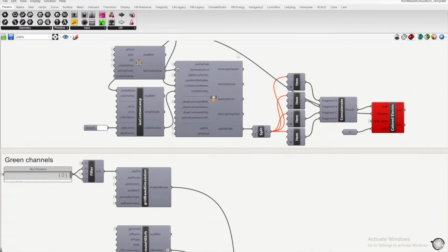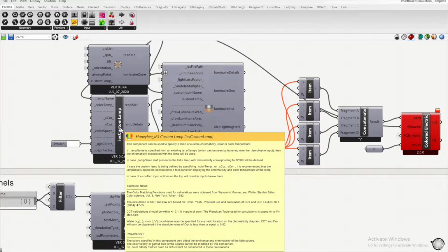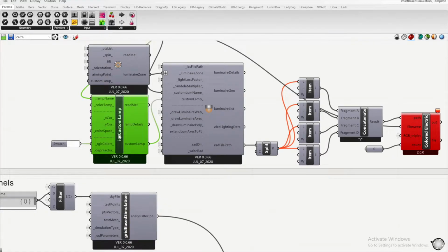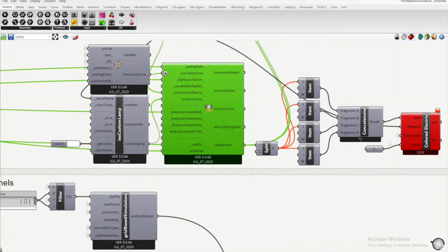It is by default included in the point-based and image-based templates, but in case you are building your own templates, make sure that this component here is included. So basically, in this component here, the electric lighting one, there is a function IES2RAD, a Radiance function, which if it detects the type of luminaire from the IES file, it will assign it specific RGB color coordinates, which we don't know. We want these color coordinates to stay at 1 1 1 so that we can apply the rest of the spectral simulation workflow for the electric lighting source, right? And so we need this to be 1 1 1 for that.